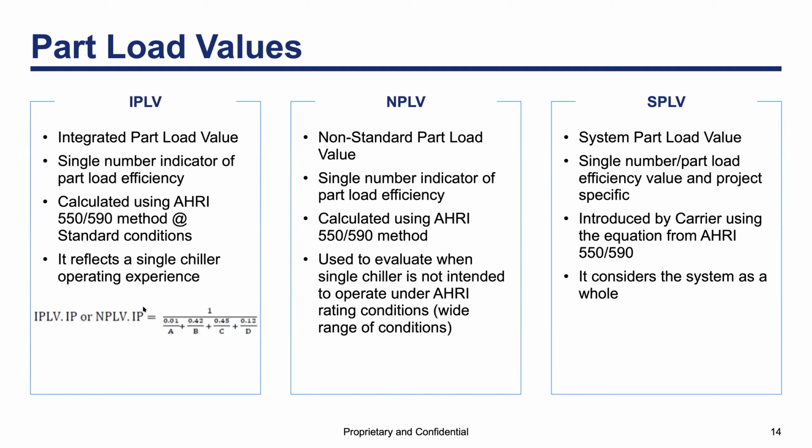The SPLV provides a much better picture about the system's efficiency and energy consumption, because it is calculated considering everything in the system, not only the chillers, but the pumping power, cooling tower, type of hydronic system, whether it's constant flow, VPF, primary and secondary, load profile, and definitely climate conditions. So think about this, climate conditions.